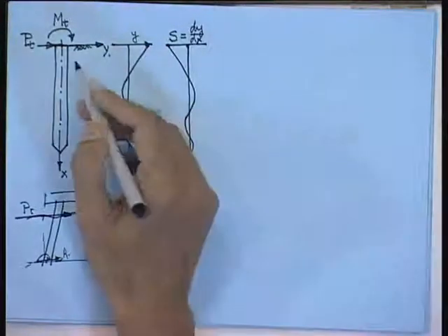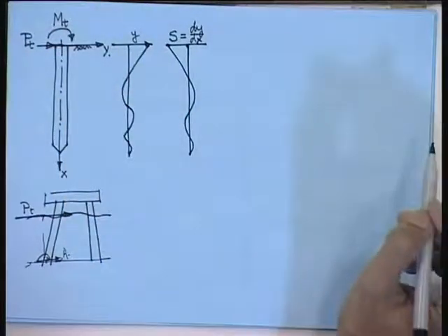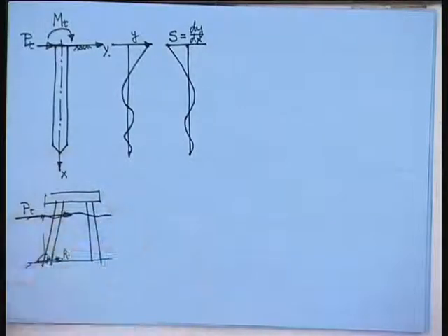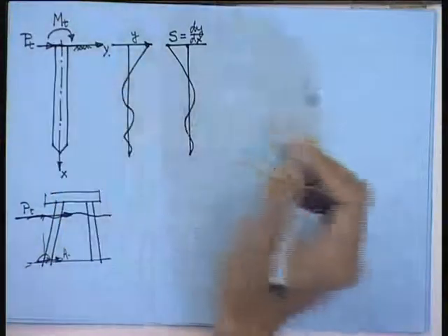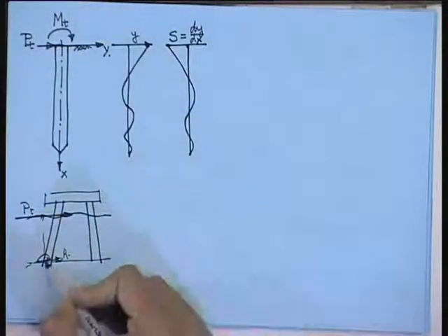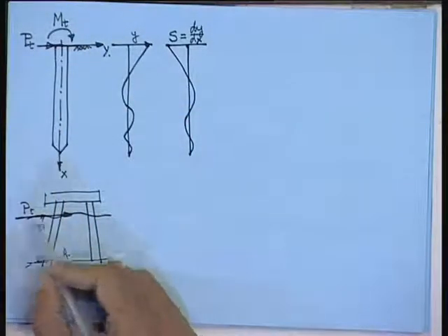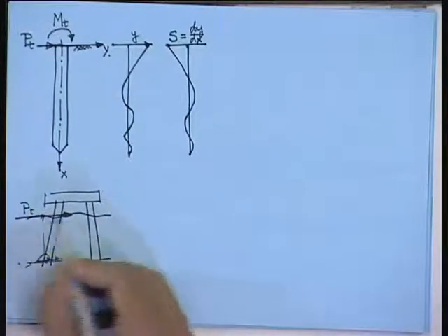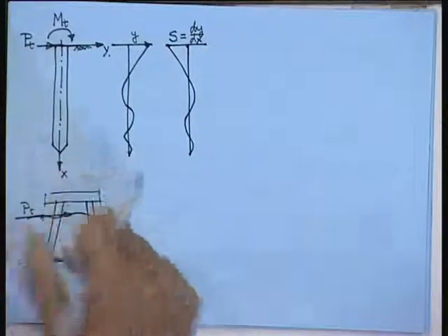So let us study the simplest vertically loaded pile. I have not given any axial load also. This is just, say, the moment that is coming from the waves. So you have taken this at the seabed. Obviously at the seabed you get one force and a moment. If you take an equivalent force, you put it equal to P this side, so you get a force on this side, and this couple will be turning, isn't it?